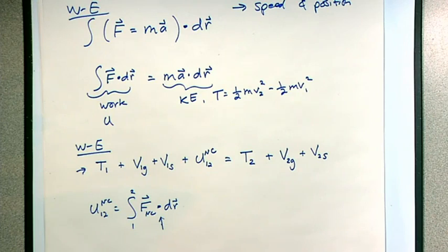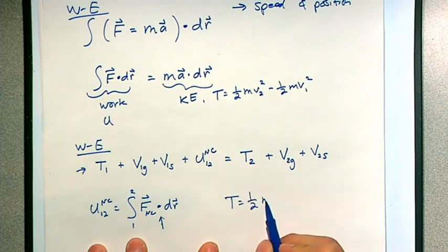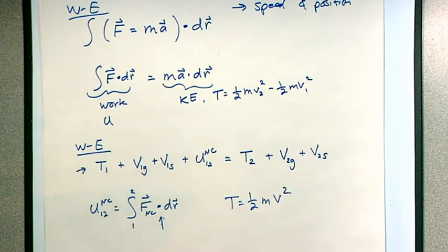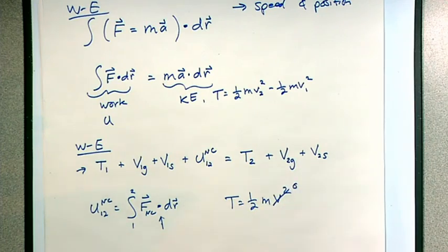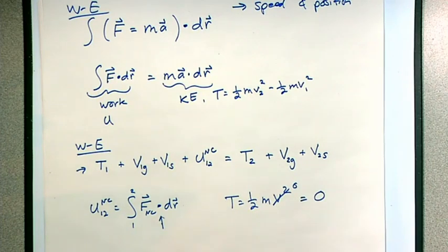If you imagine that this thing is spinning along the z-axis, which is fixed, our old method would say T is equal to half m v squared. Well, at the CG, the velocity would be 0, because it's pinned along that axis that it's spinning about. So we'd say, we've got no kinetic energy from this thing spinning.